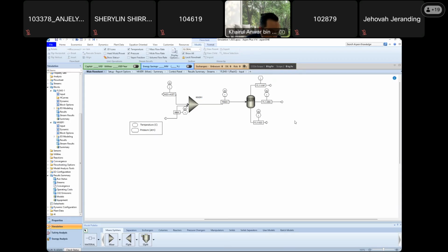The separation process consists of extraction of the acetone from water into methyl isobutyl ketone, which dissolves acetone but is nearly immiscible with water. The overall goal of this problem is to separate the feed stream into two streams. This is the feed stream. The two streams should have greater than 95% purity of water and acetone. So you need to get 95% on water here.